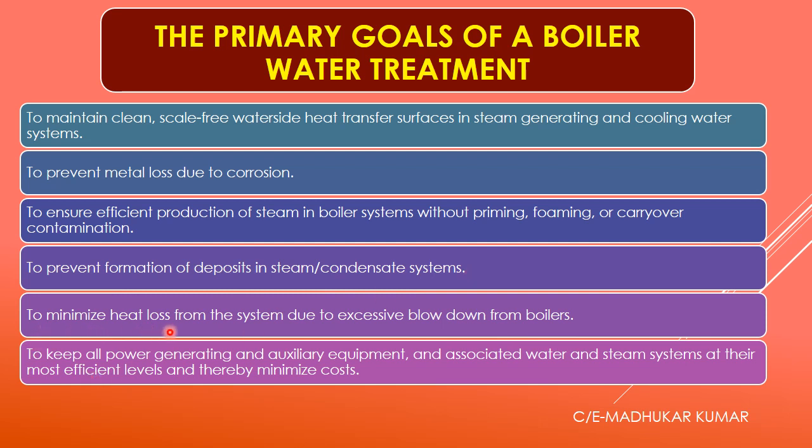To minimize the heat loss from the system due to excessive blow down of boilers. This is also one of the problems. Not only the heat loss, your chemical properties or the additives which you have added earlier will be gone with the blow down. Blow down basically means removing water from the boiler, because the condition of the boiler water is not as per the desired specifications.